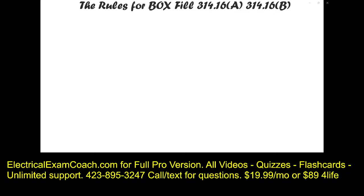We're going to learn how to count conductors now for our box fill calculations. We have to accommodate for each wire and then also for the different devices and fittings that we use out in the field. We're not going to be dealing with equipment grounding conductors at first. We're going to calculate those separately at the end of this slide. So now we're dealing with only neutrals and hots. Each conductor counts as 1 of whatever gauge it is. So each 12 counts as 1, each 10 counts as 1, whatever gauge wire it is.